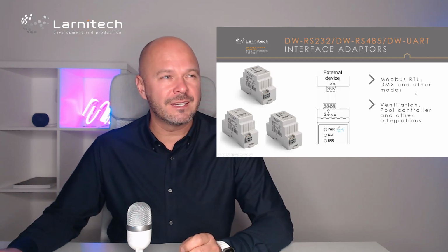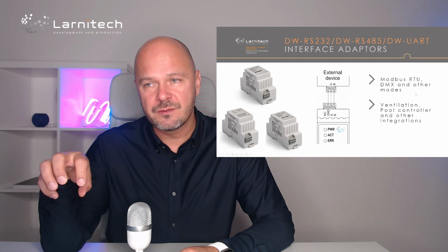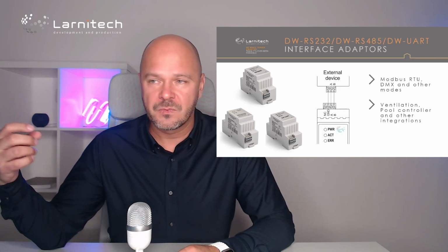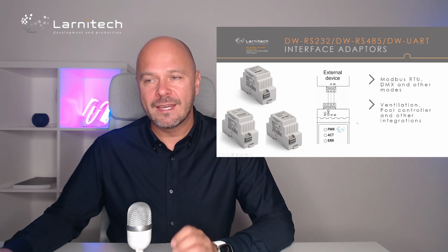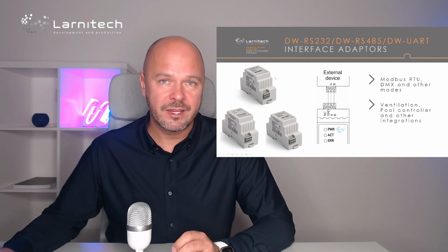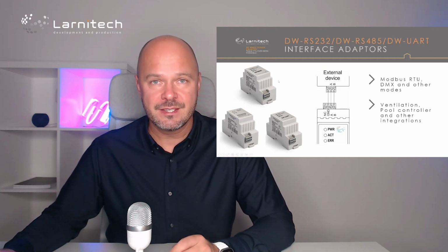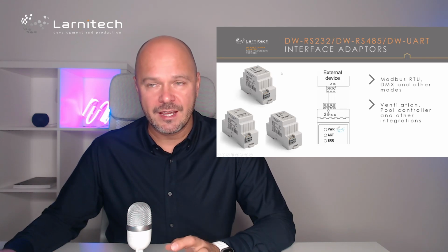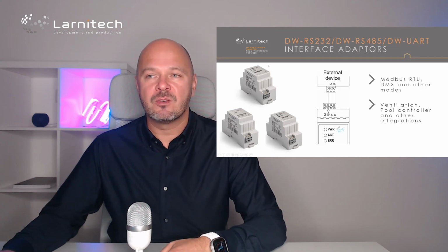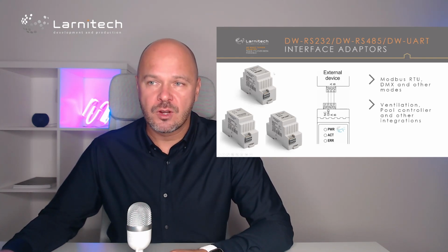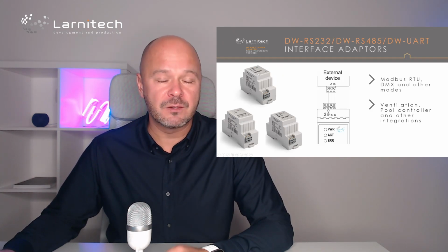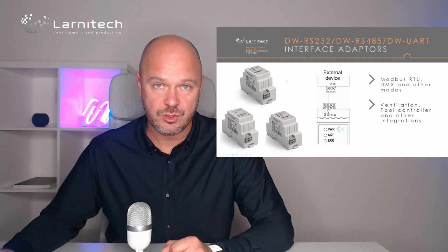Some people ask, can we use standard drivers for them, or do we need to make our own drivers for third party? You can make your own drivers, or you can use standard ones. We have the list of compatible devices which already have the drivers. So, for example, for this RS485 we have drivers for external thermostats from different manufacturers like Siemens or Danfoss.